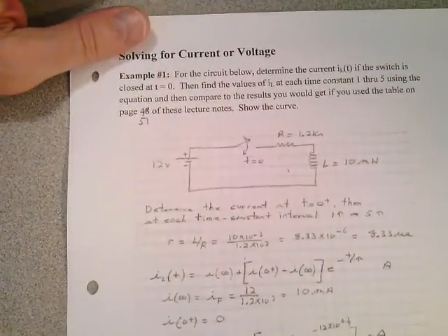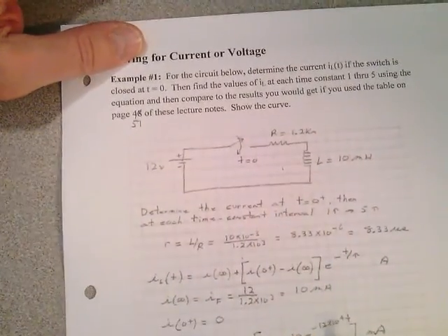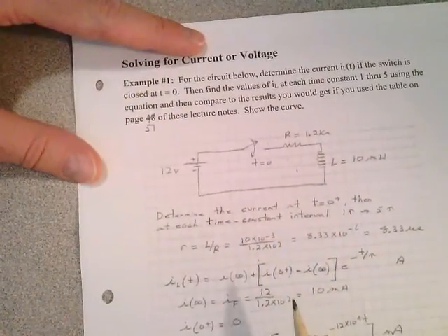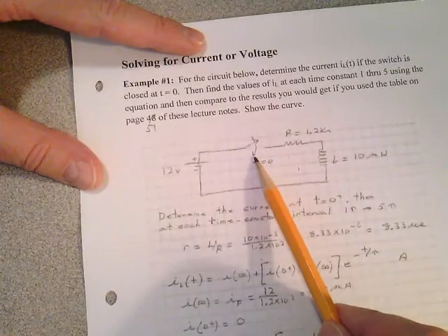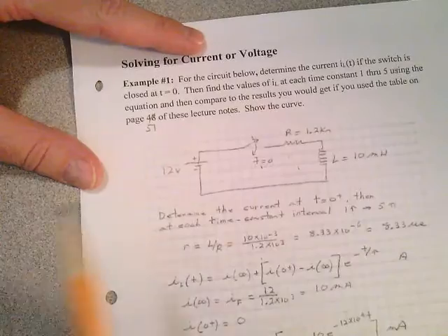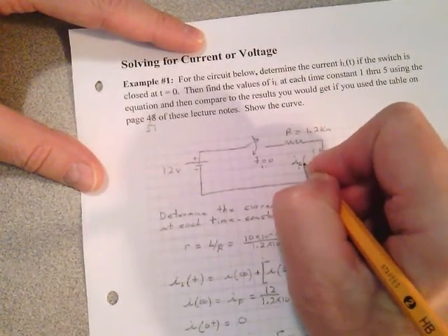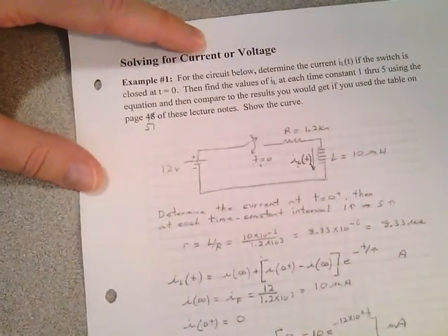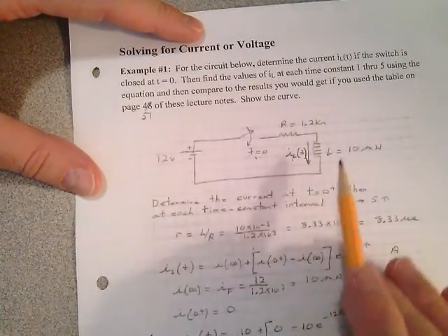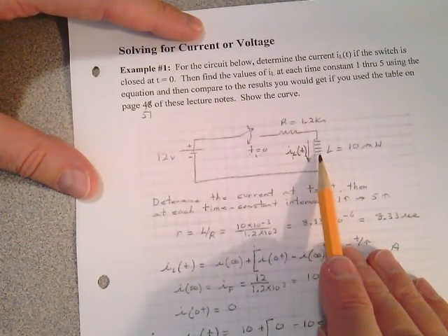So here's the circuit. There's no initial condition here. There's no initial current here. This is open from minus infinity up to t equals 0. At t equals 0, you close that switch. And I want to know the current in this inductor. I want to know the current here, I L of t. Let's use some common sense here before we go through this. I want you to take a look at this, and is that current going to have a rising exponential or decaying exponential?